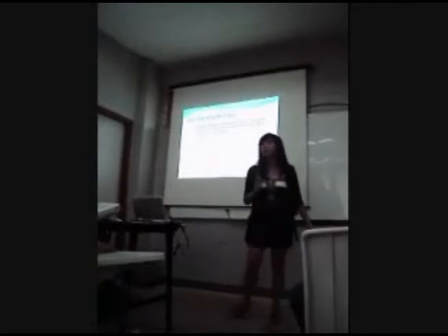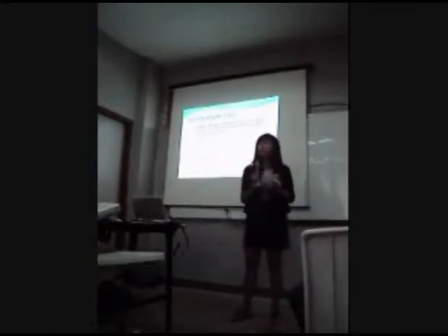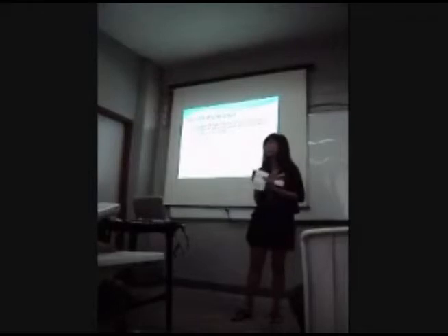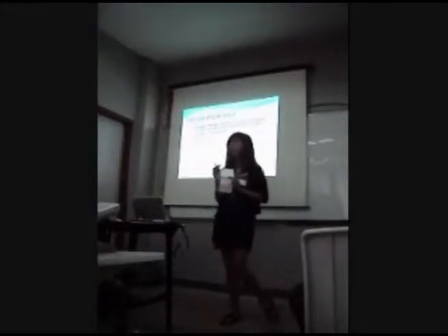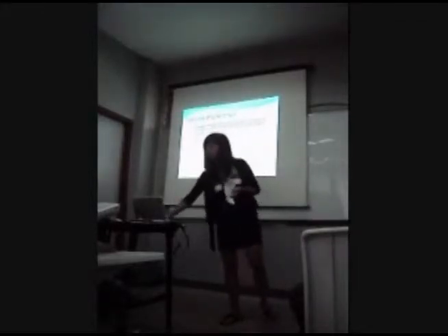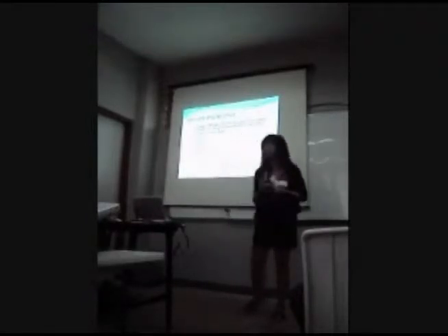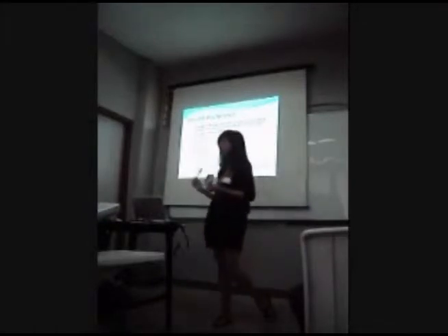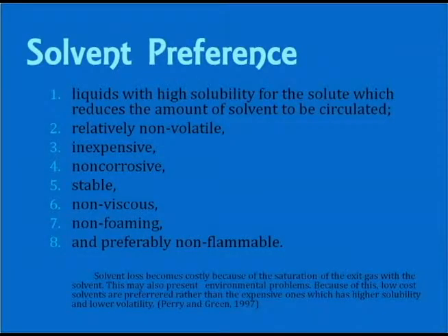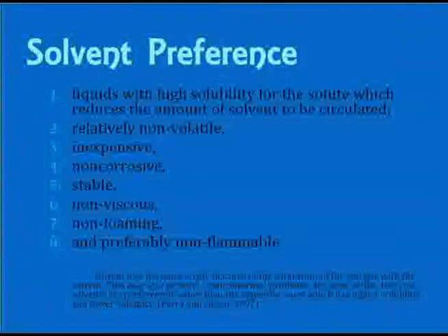So as we know, the solvent is perhaps the most important part of the gas absorption process. In choosing your solvents, here are some of the considerations to make. The liquid should have high solubility for the solute, which reduces the amount of solvent to be circulated. It should be relatively non-volatile, inexpensive, non-corrosive, stable, non-viscous, non-foaming, and preferably non-flammable.